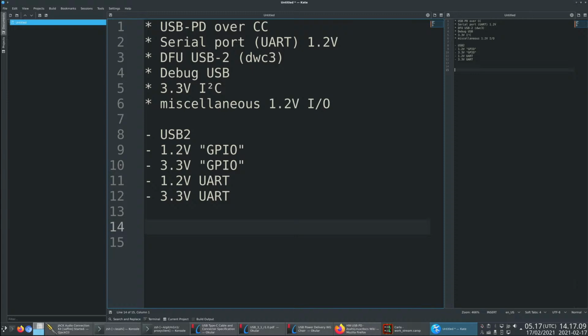So we're going to have some kind of microcontroller here, and I want to be able to use a hardware UART for these modes. And for I2C, it would be nice to use the internal I2C peripheral, but I'm not going to make that a hard requirement, because we're going to have some restrictions as to where the pins map, and I don't want to complicate this too much. I'm happy saying that if we can get a GPIO on those pins, we can do I2C with that. And same with SWD.